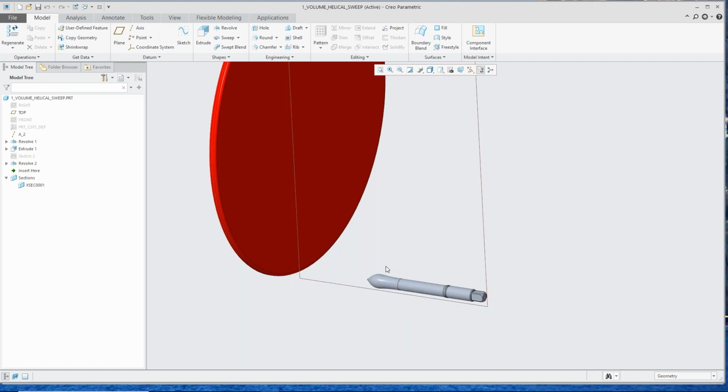And so they've taken that capability and put it into regular Creo. So now you don't have to think ahead so much as far as when you put rounds on it. It's still a good idea, from a modeling practices standpoint, to do rounds and chamfers near the end of the development of the product. But in this case, sometimes you have to put rounds and things in early. This will still give you the capabilities to add draft onto surfaces that have edges with rounds or chamfers.